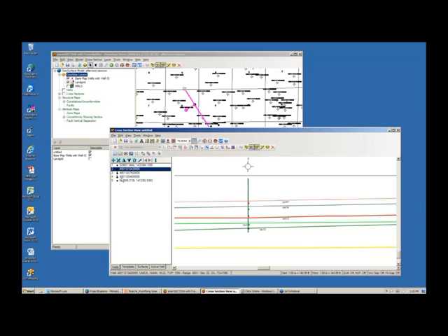You can always change the position of a well by clicking the up or down arrow. We can flip or reverse the order of the cross-section, and if we did have deviated wells, we could even flip the well bore orientation. So there are many different things you can do here in this Wells tab.